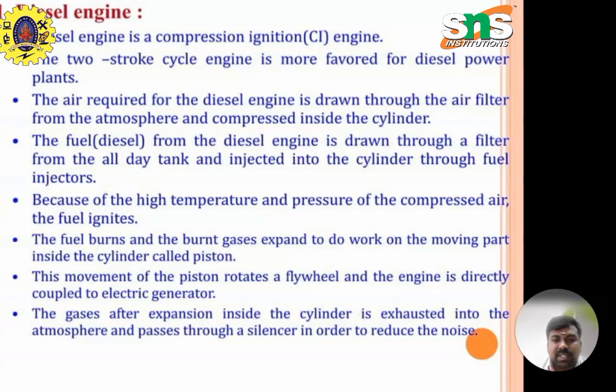Because of the high temperature and pressure of the compressed air, the fuel ignites. The fuel burns and the gases expand to do work on the moving part inside the cylinder, called the piston. This movement of the piston rotates the flywheel, and the engine is directly coupled to the electric generator. The gases after expansion are exhausted into the atmosphere and pass through the silencer in order to reduce the noise. This is the working of a typical diesel engine.